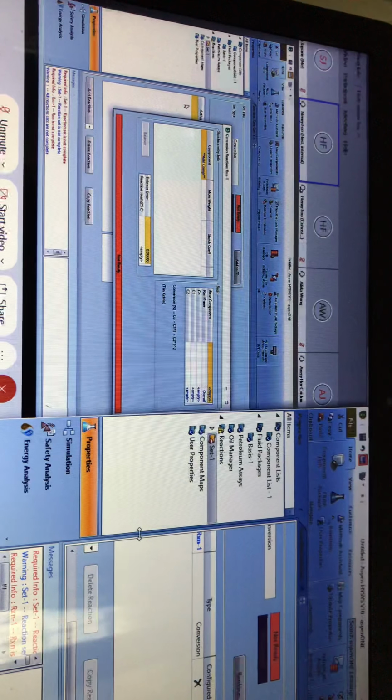Then you can double left-click on Reaction 1, which will lead you to another window, which is the detail of Reaction 1. In this window, you will need to key in the information required to define the stoichiometric reactions.